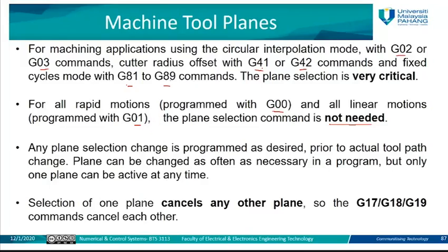So selection of one plane here will cancel any other plane. If you select G17, for example, that means G17 will cancel G18 and G19. If you work on the XY plane, you cannot work on XZ or ZY. If you want to work on XZ, you need to use this other command.